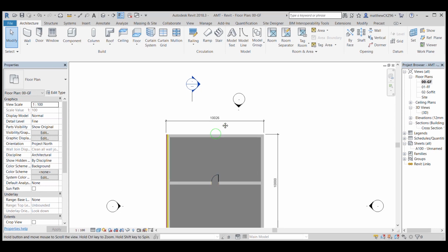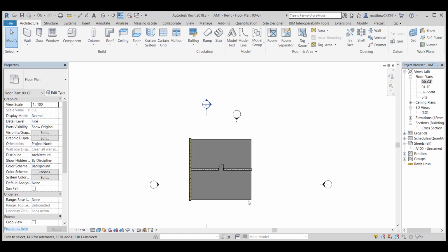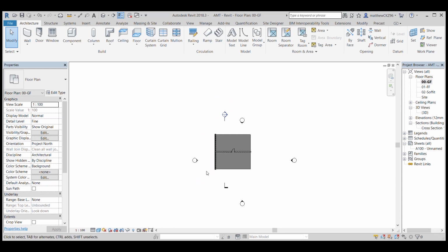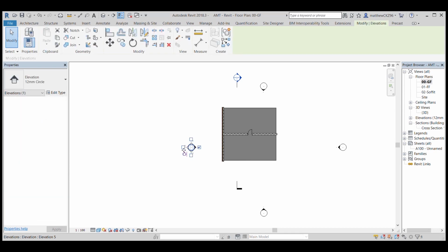Right. Go ahead and delete these walls. So click on this wall once, and hold down Control while you do it, and this one, so select some more, and press delete. We are now going to draw a series of external walls to make our floor plan. So let's drag this elevation mark out a little bit first. Click on it and hold, just drag it out right here.